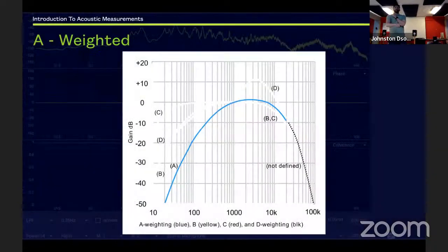Now this is a graph of an A-weighted scale. You all can see the screen clearly, right? Yes, sir. Can you see where the filters are? Somewhere around 4 or 5K, it starts dropping off. It's not to scale, but it'll give you an idea. And somewhere below 500 hertz or so, it starts dropping again, right? There's a high pass filter and a low pass filter added on.